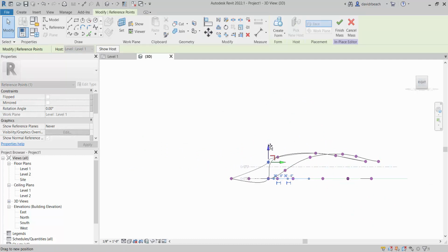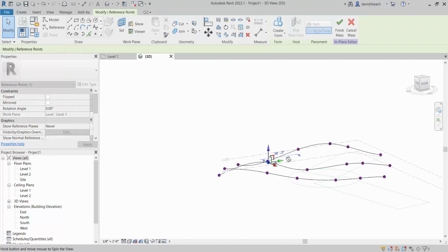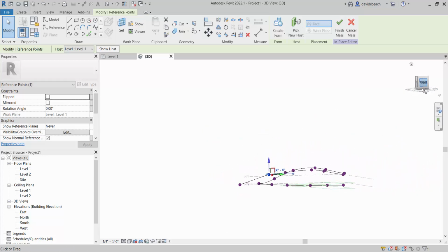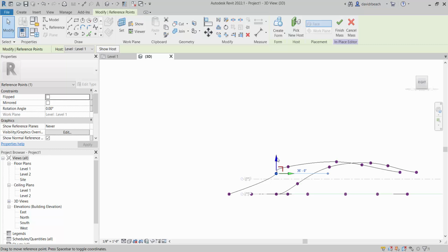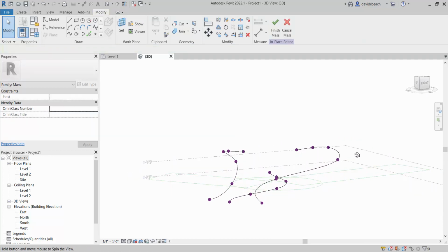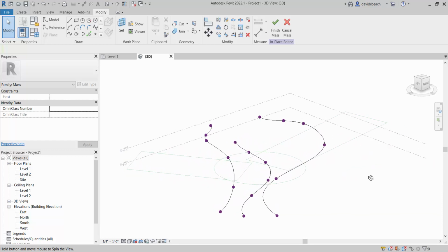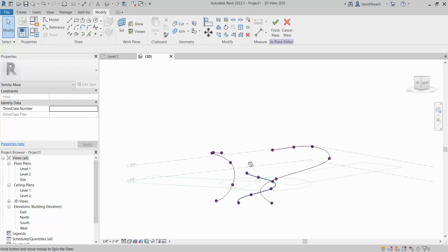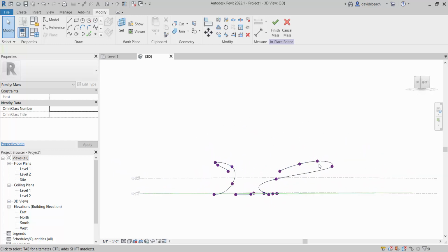And even then, if the tab key is not working well for you, often you need to switch to a wireframe view as well in terms of selecting some of these forms. Let's pull that down just a little bit. So I've got those two edges. And so if I built this form right now, I would have a strong edge and a strong edge, but it would kind of do a little bit of an arc between these probably.